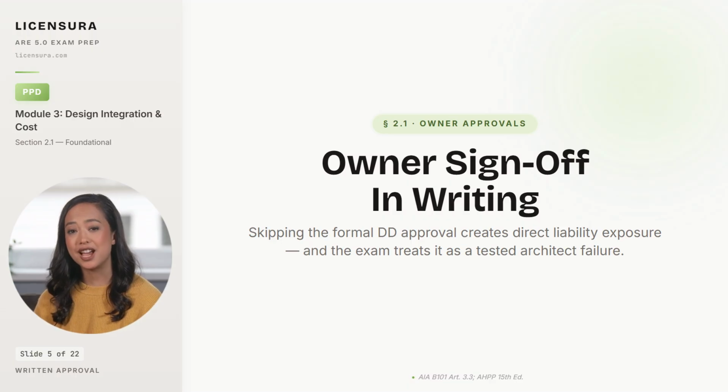Here's the question every architect should ask before moving from DD to construction documents. Did the owner sign off in writing on the DD set? If the answer is anything other than yes, you have a problem. AIA B101, Article 3.3 requires owner approval at the end of every phase before you begin the next one. And that is not bureaucratic theater.